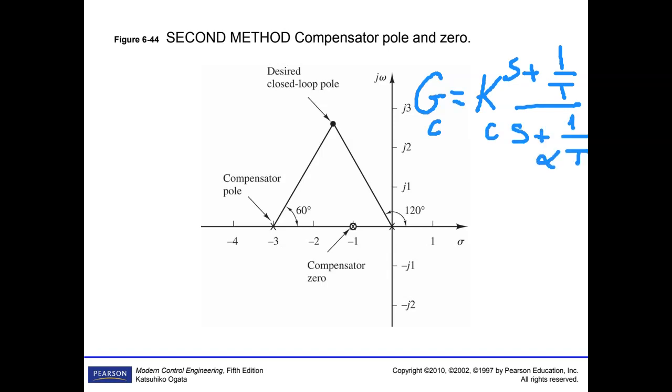So that's lead, alpha smaller than 1. That means you are actually putting 1 zero here. Let me show in red. Now your system has got a pole already here, and you are not happy about that pole. You would like to get rid of that pole. So you are adding a 0 here. As long as you add a 0 here, you get rid of that pole.